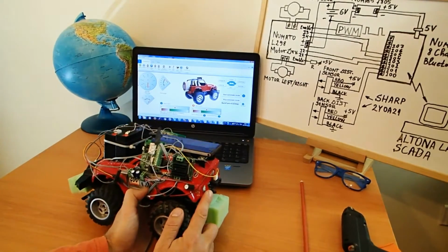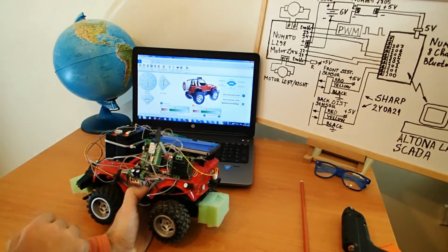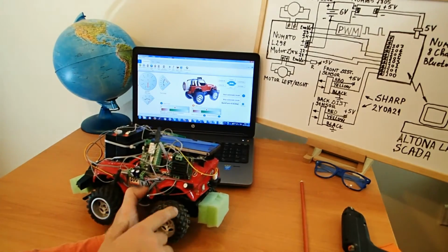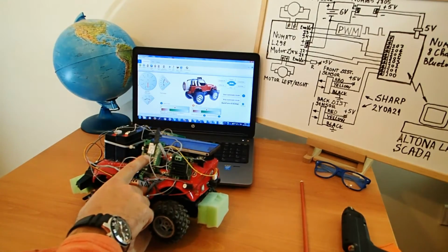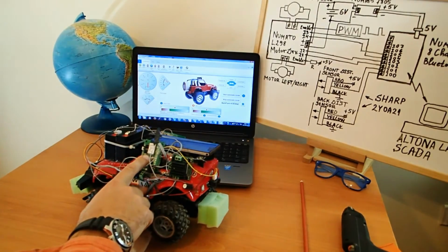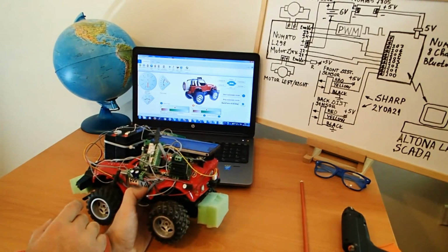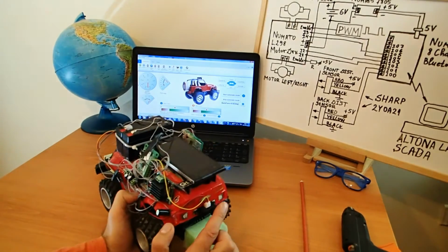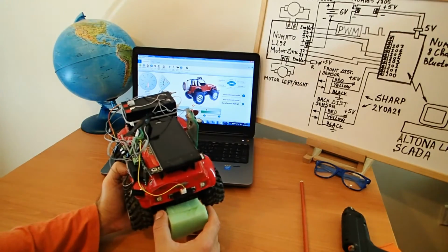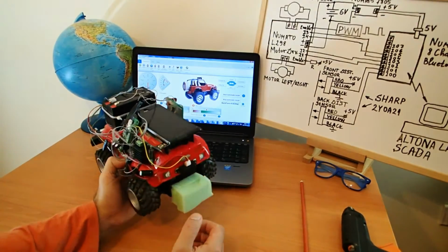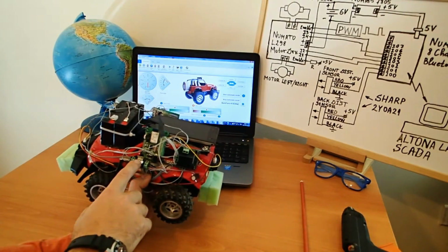For this project we need an old radio controlled car. We will use only its DC motors, DC motor driver to control the DC motors, Numato Bluetooth device with 8 GPIOs. We will use 4 of its digital outputs to control the DC driver and 2 analog inputs to read the values from distance sensors. The distance sensors work in range 10 to 80 centimeters and have analog outputs, battery and 5-volt voltage regulator.